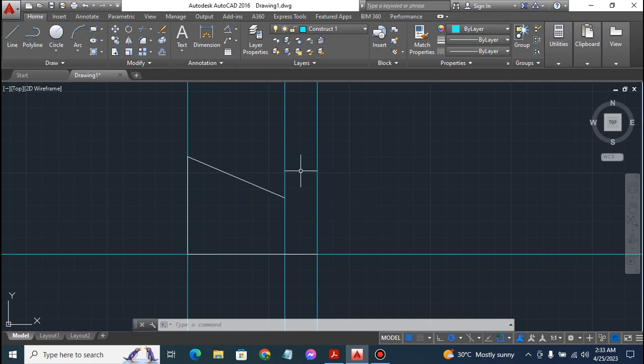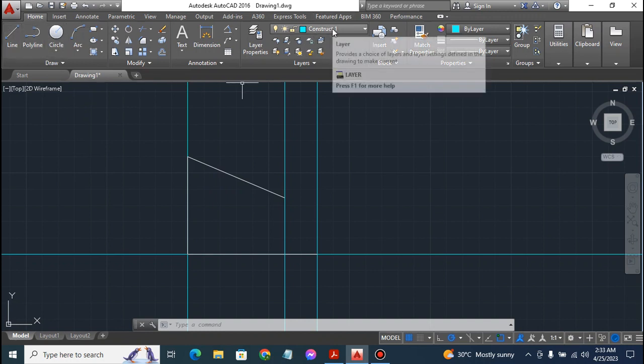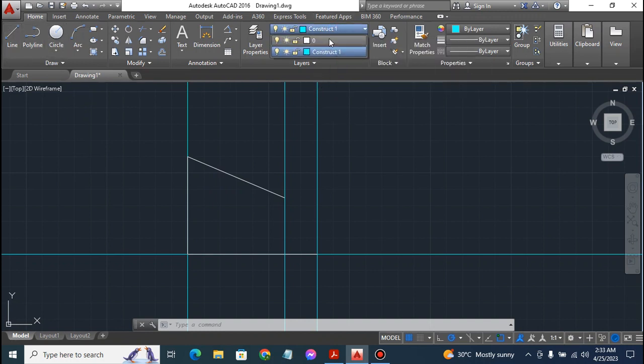So our next line, in order to get the remaining part of the angle that will make it 99 degrees, our second line should be at an angle of 58 degrees. Okay, 58 degrees. You subtract that 32 degrees from 90, we'll have 58 degrees remaining. Okay, so let's do that. Go back to our main layer, go to the layer toolbar, click on the drop down menu, click on the main layer, which is 0 layer. Okay, we are on our main layer now.